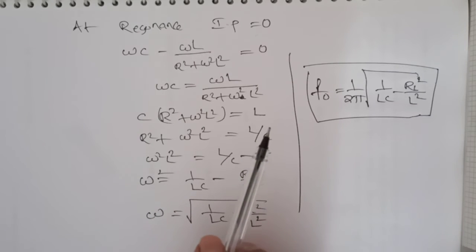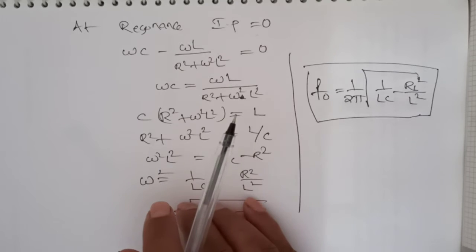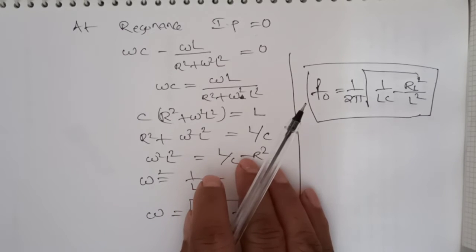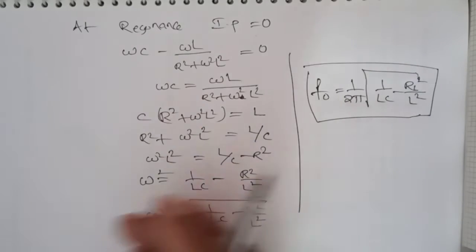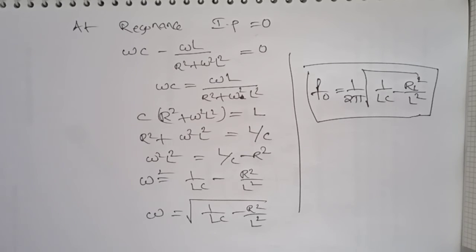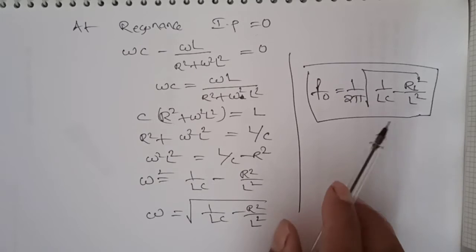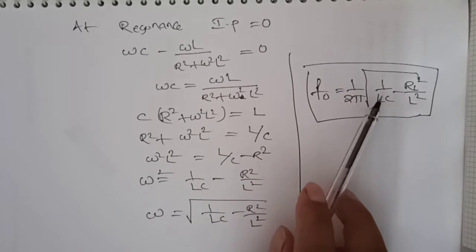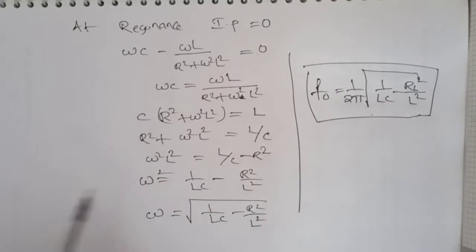The impedance of the circuit can be obtained by putting the susceptance part equal to 0 in the expression. By using those equations we can find the terms. If the resonant frequency is given, we have to find one of the parameters, either L or C. For such conditions we have to use this mathematical formula.